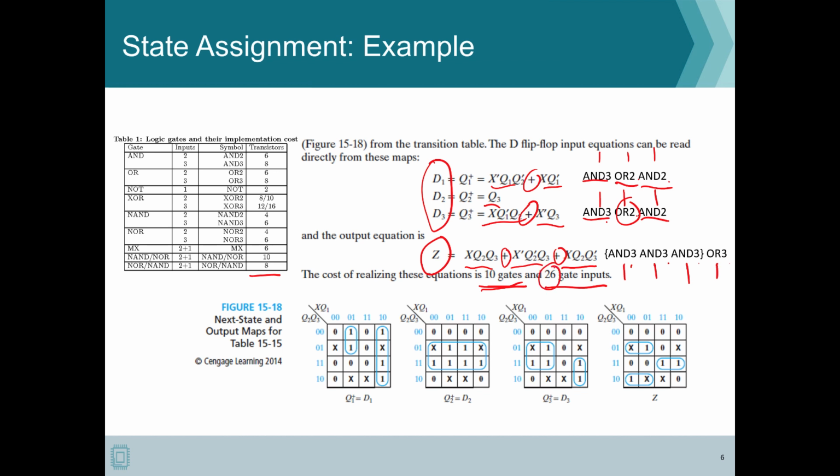And now if you want to create it in terms of transistors, here is a table. Usually the NAND will give you the smallest, or the NOR, and you will need to use an inverter to get the AND, which is 2 more transistors. So you can take AND 3, look this up, and then you can put 8 transistors for this case.